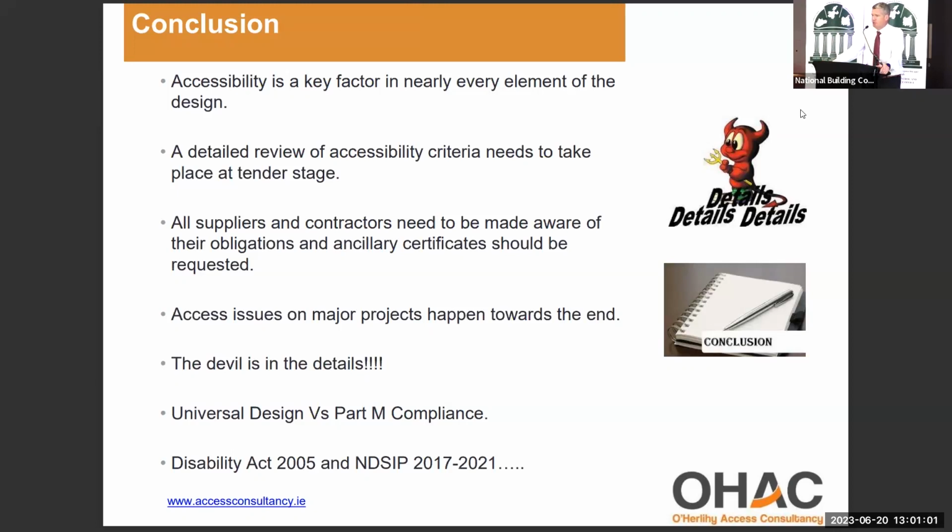Access issues on major projects happen towards the end. That's when everyone is rushing. That's when things are going to go wrong easily. The devil's in the details. There's so many things that can go wrong in relation to accessibility, particularly the small detail like the position of the alarm reset or the alarm pull cord and stuff like that.